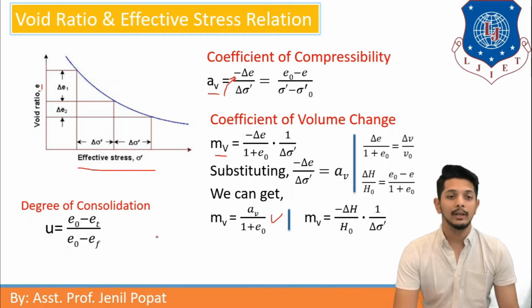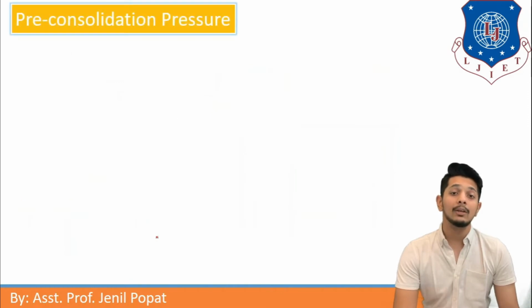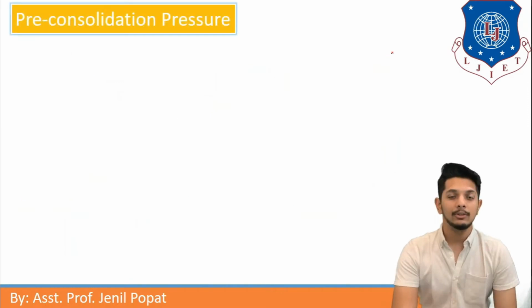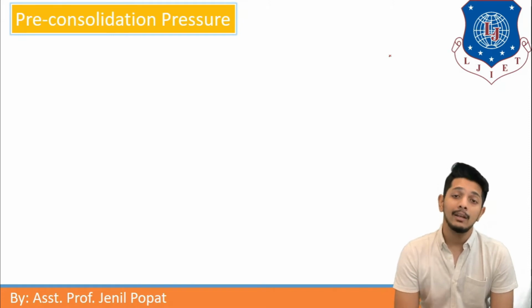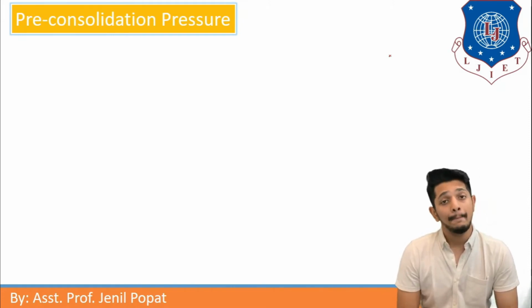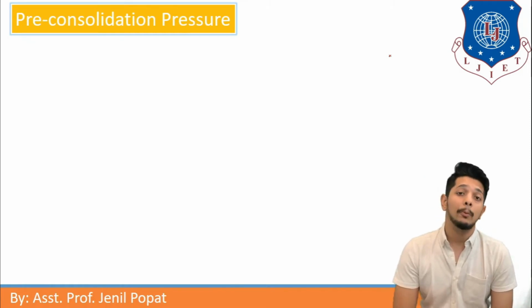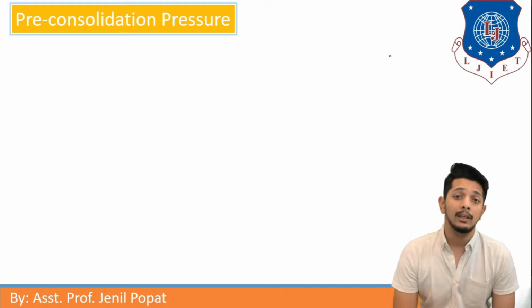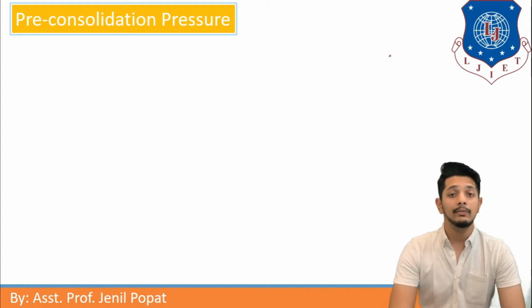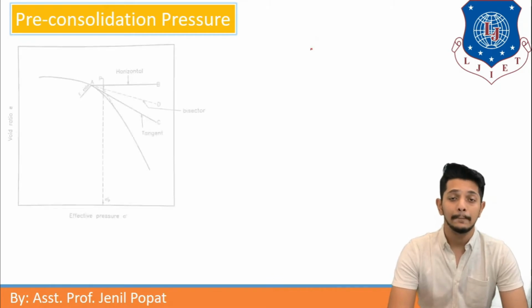Let us move forward to pre-consolidation pressure. Pre-consolidation pressure is nothing but the temporary overburden to a soil which has been subjected to an external load and under which it is consolidated. Now, pre-consolidation pressure is very important to obtain. For determining pre-consolidation pressure, Casagrande has given an empirical theory.